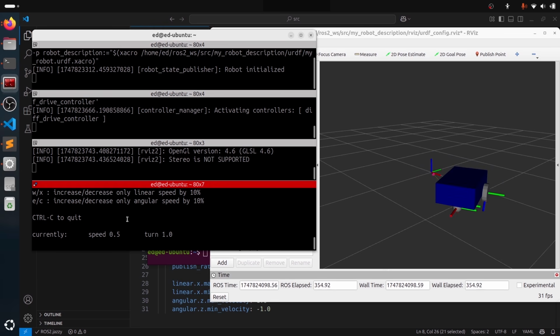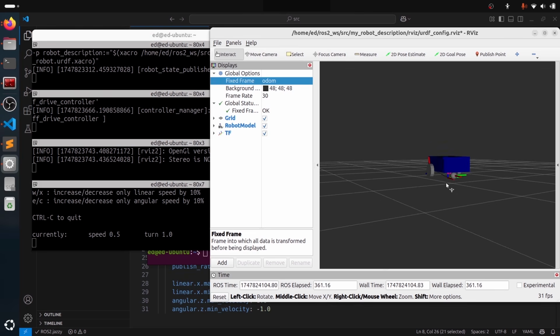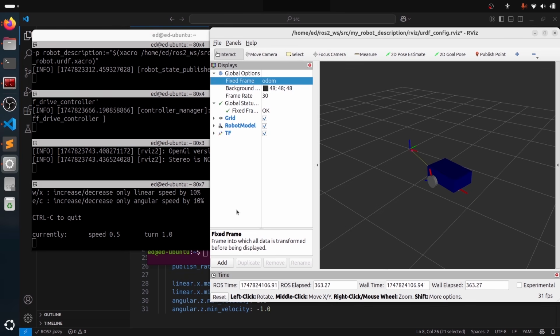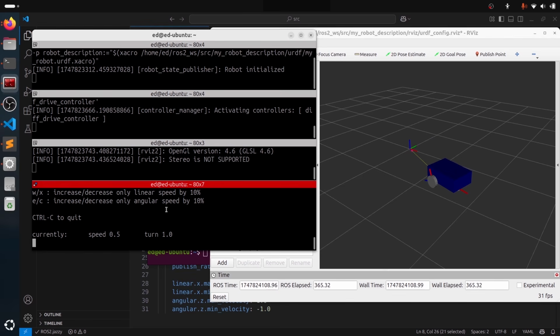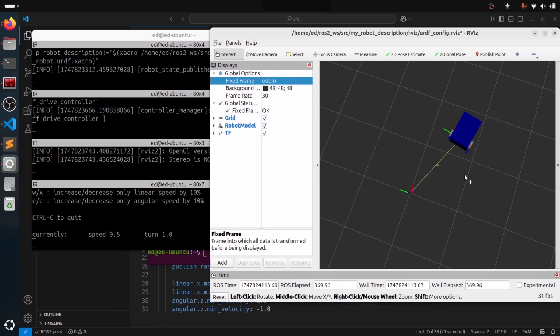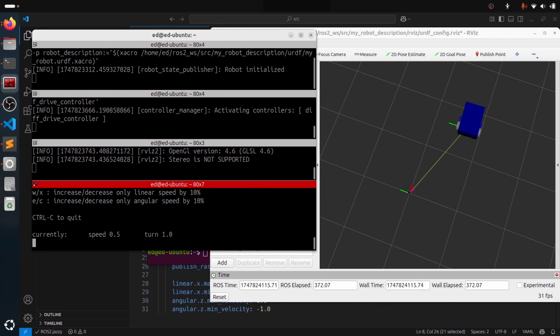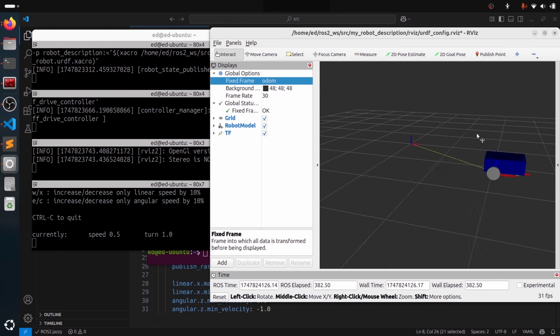Great, our robot, even if the hardware is a fake hardware, we have correctly configured the controllers and kind of the stack with ros2_control and the different nodes we need to start so that we can use ros2_control with our robot. All right, you can see it's working. We see the wheels are turning, and we even have this new TF, odom to base_footprint.